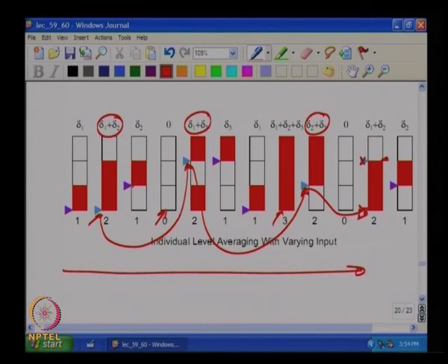yes, okay, which means that at DC you will have a notch, at low frequency it will go as 1 minus Z inverse, okay. So, this still does not mean that there is no harmonic distortion, right, because it is not clear at least from the discussion we had that these thermometer drive waveforms are linear functions of the input.